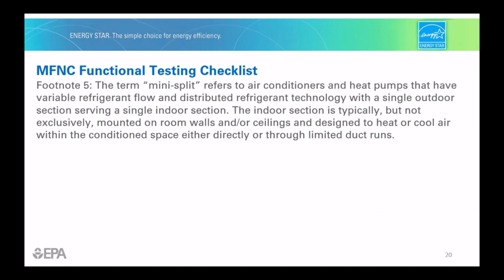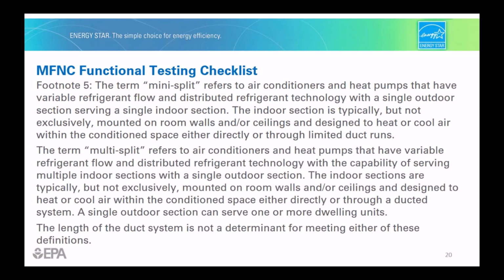This is a footnote that provides Energy Star's distinction between mini-split and multi-split systems. In general, the mini-split is a 1-to-1 configuration, whereas the multi-split is one outdoor unit to many indoor units, which may serve one or more dwelling units. While exempt from the requirements in Section 2, refrigerant charge testing of multi-splits is addressed later in Section 6.